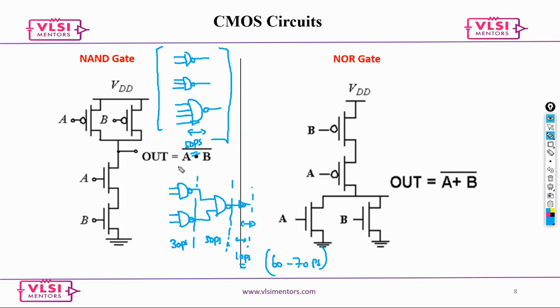Also, there is logic level 1, logic level 2, and logic level 3 if you have to add it. Now the answer depends on the frequency of the design. My tool might pick a four input NAND, or a three input NAND, or it can even optimize the four inputs depending on what kind of inputs there are, and if there are any constants. So it might optimize the cell, but in this scenario we always try to prefer NAND 4.